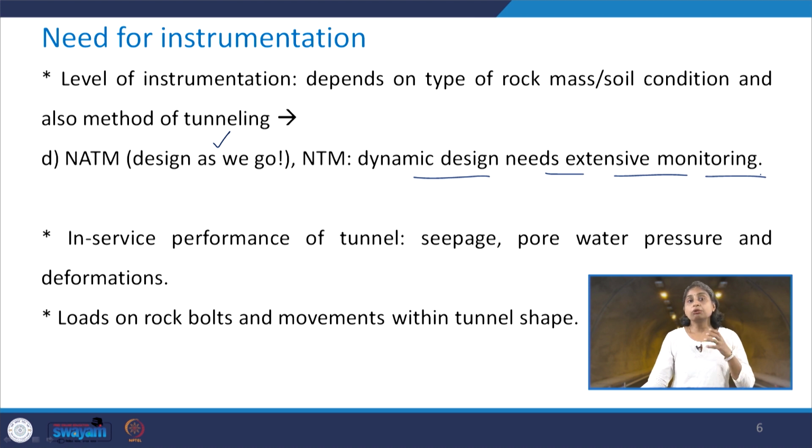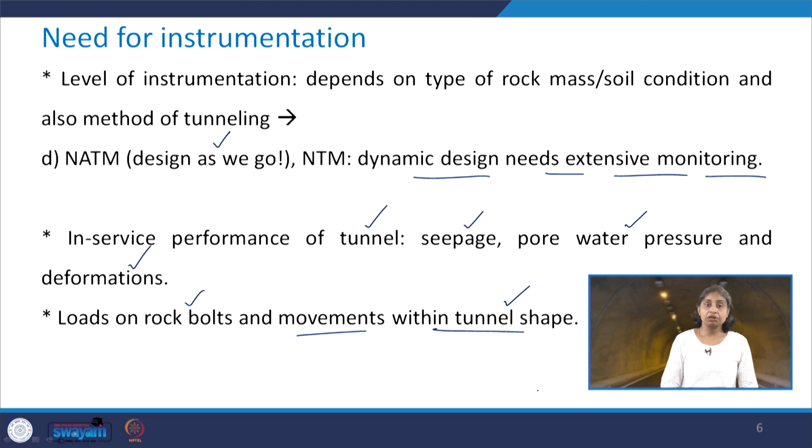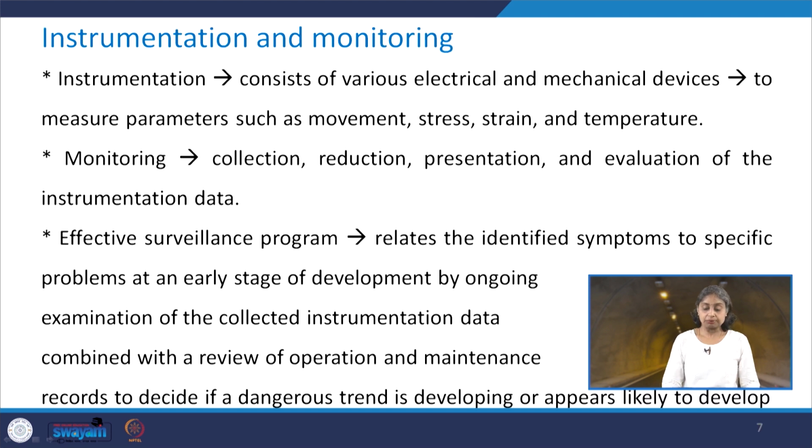Not only during construction is instrumentation and monitoring required, but also to know the in-service performance of underground excavations, say for example tunnels, such as seepage, pore water pressure and deformation. We should go for instrumentation and continuous monitoring of the performance of the tunnel. Further, loads on the rock bolts and movements within the tunnel shape can also be observed using proper instrumentation.